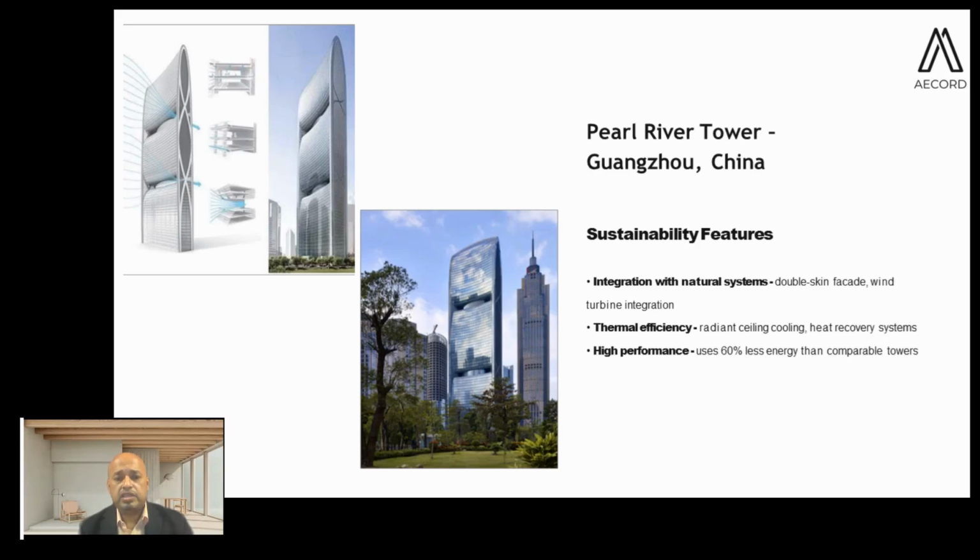And thermal efficiency. So this building was built some years back. So the radiant ceiling cooling. We know that today in India, radiant cooling is talked about, but really not done much in projects, other than a few corporates like Infosys, who have made it a mandate for all the tropical climate, other than humid climate or coastal climates. But yeah, radiant cooling is the most efficient way of cooling, and heat recovery systems are there, but we really don't see that as a part of design.